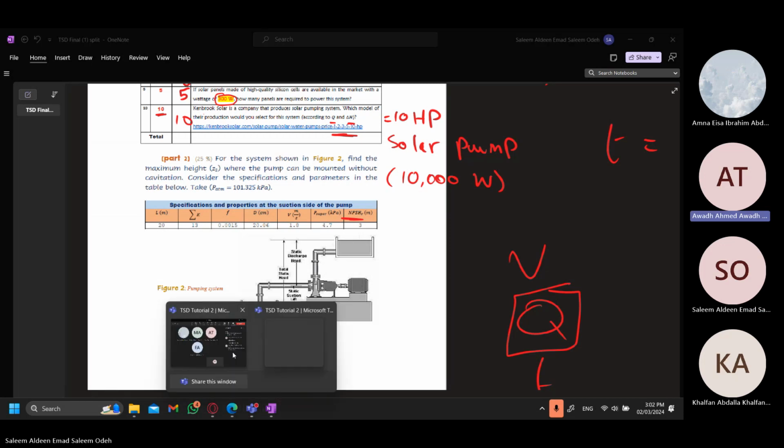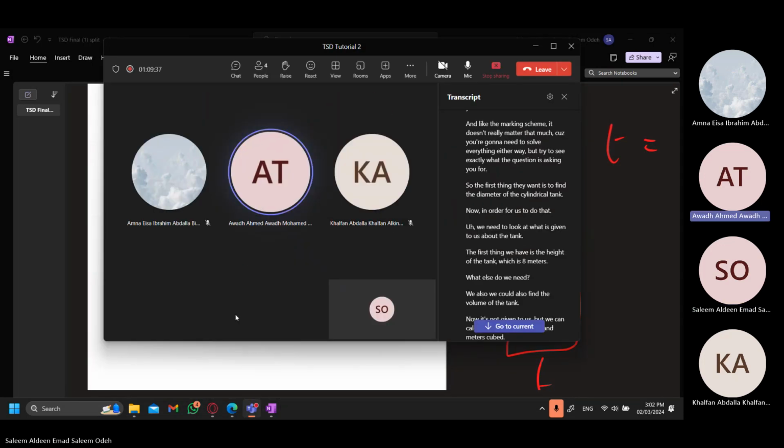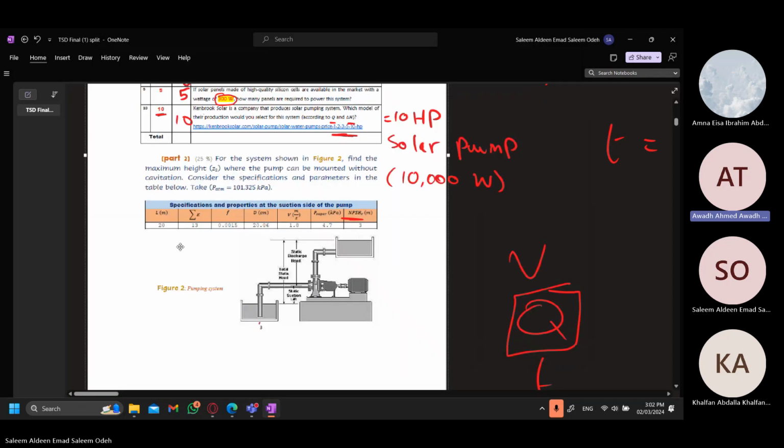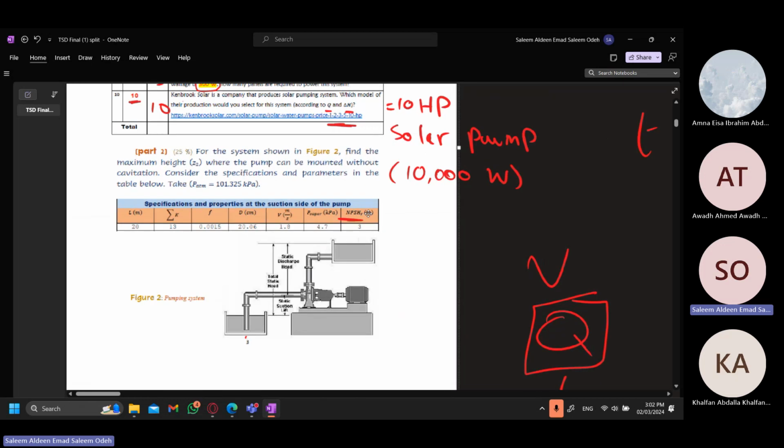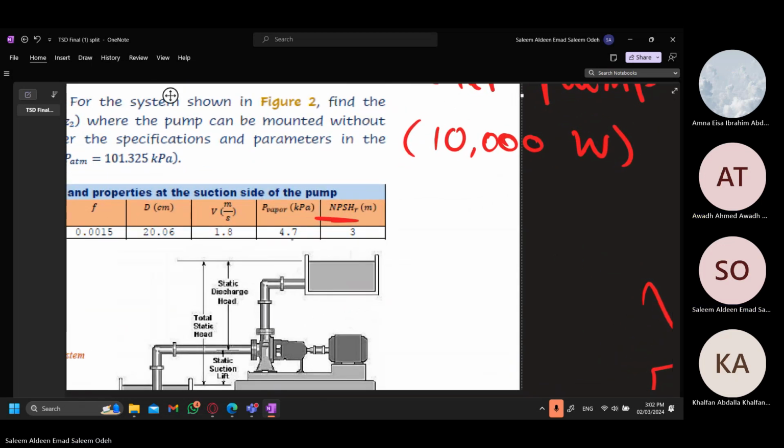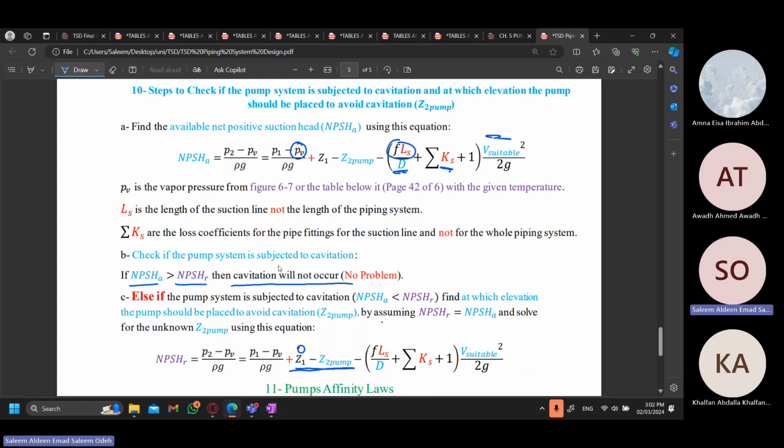Assalamu alaikum. I do have a question. Go ahead. Can you just repeat why did we use the equation NPSHR, not the other one, the both equations which are similar? Because that's the given NPSHR. They gave it to us, the required net positive suction head. Now, if in a different question they told us to calculate the net positive suction head, then we'll end up using this equation.